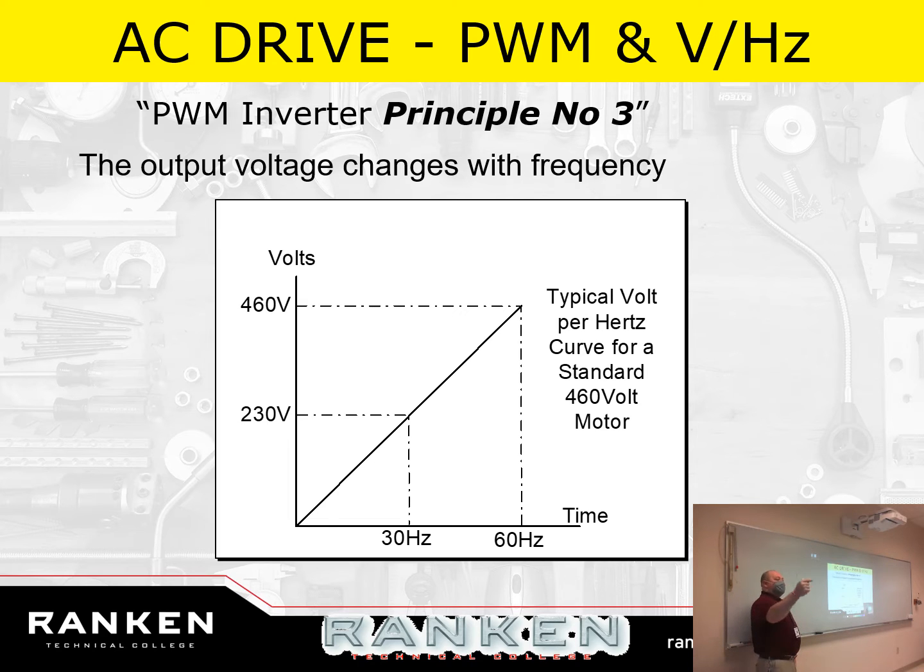So if you take your voltmeter, your Fluke meter, and put it on diode checker, in one direction, in one polarity, you're going to get essentially overload, or infinite resistance. Okay? If you flip the polarity, you should get very little resistance, almost zero.